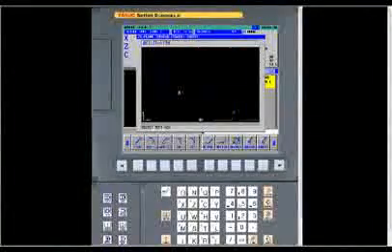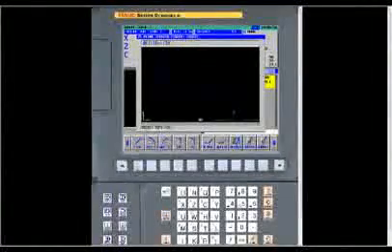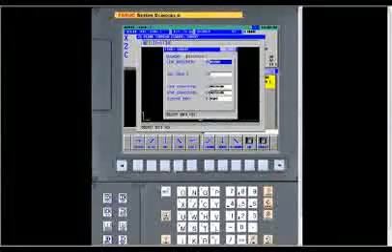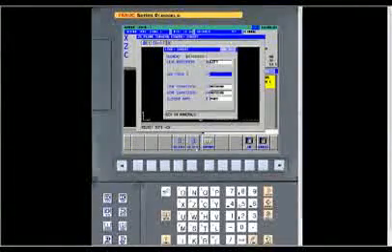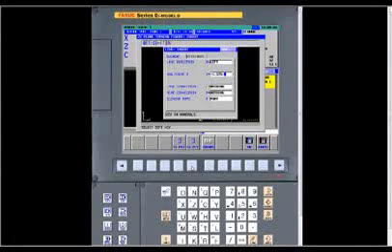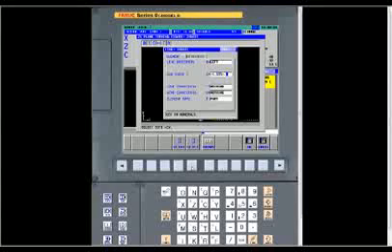Say OK. It didn't draw that yet because we didn't know where to go yet. So a line to the left. And if we press the start point minus incremental, it remembers where we were. We want to go another 100 thousandths, so 0.1. It does the math for you. And again, this is still part.